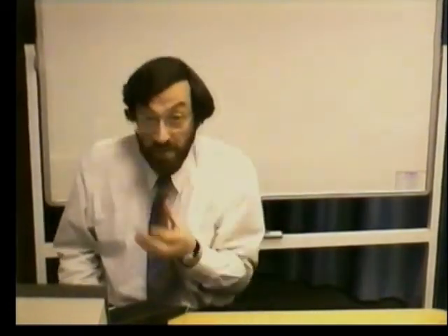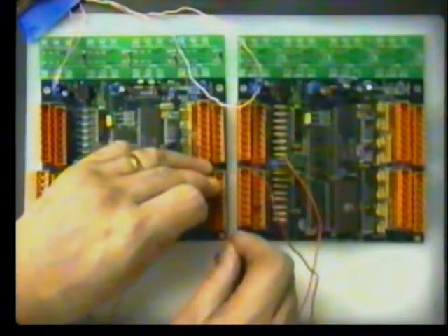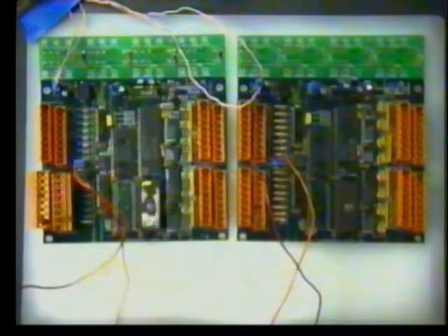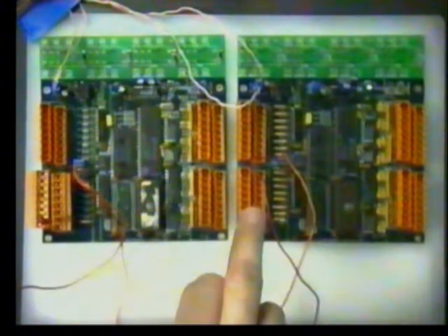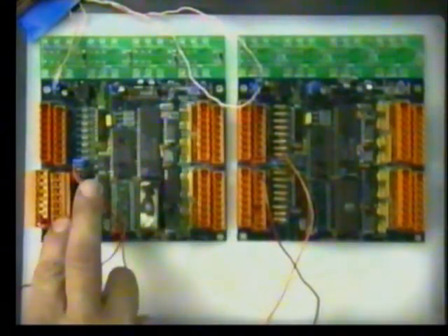And we've achieved that by creating an information channel where the broadcaster is broadcasting its switches in that channel, the receiver is mapping those switches to its outputs, and so we don't actually define the functionality of the data. The information is there in the channel for you to do as you wish, and we can do the same thing the other direction, because there is another information channel that has been defined as these switches, and hopefully if all is still working, we should see this LED coming on, because what I've defined is that channel there has been mapped to this output state there, and that switch there has been connected to that switch there.